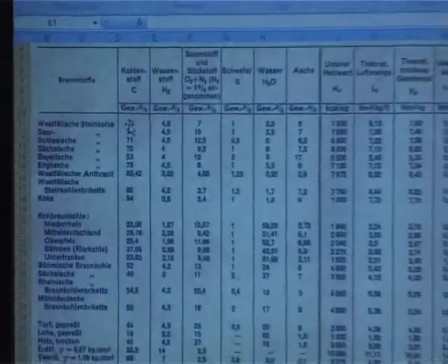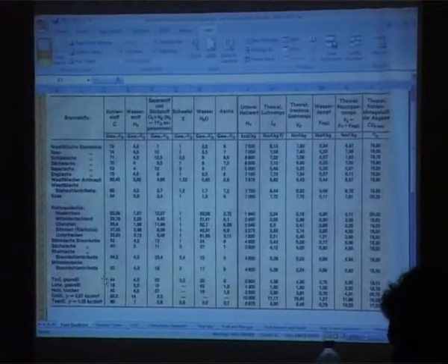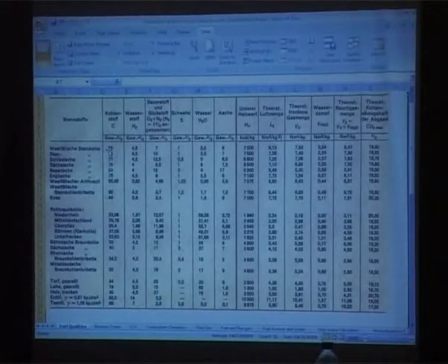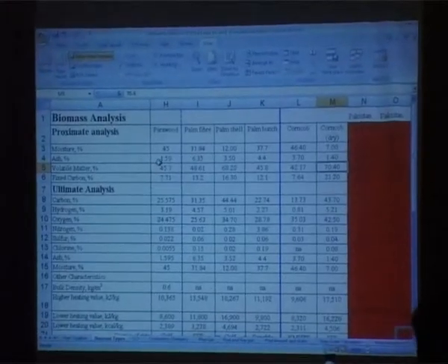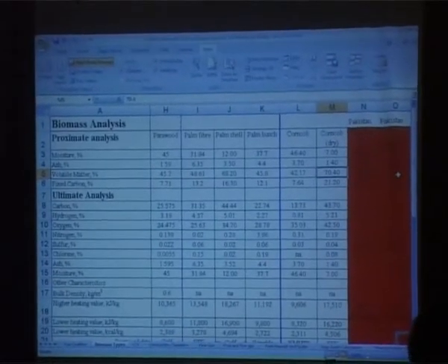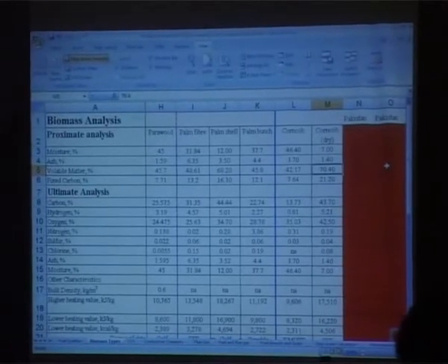So if you have coal, with very high carbon, there's very low volatiles compared to biomass. Then here you need a lot of primary air, but when we start talking about biomass with high volatile matter, then we need much more secondary air. And the balance is something you'll have to adjust when you have the fuel.